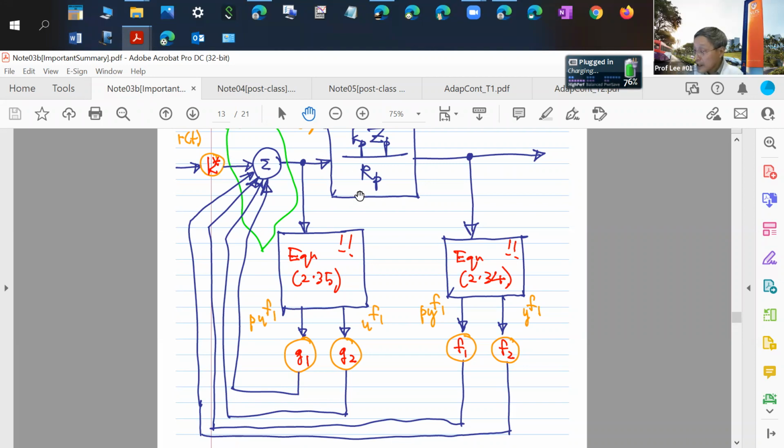So here, these two n signals form a 2n order non-minimal state realization of the system, and you're doing state feedback in the 2n order non-minimal realization, then the state variable system that you've set up remains at 2n order. State feedback doesn't change the order of the system.